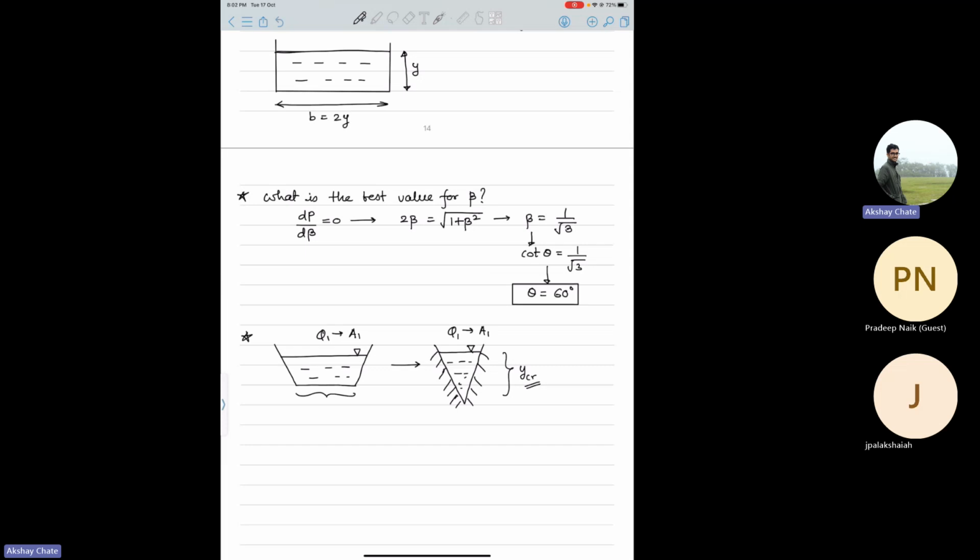But if we are talking about practical things like construction costs, there is also sedimentation, right? For a triangle, I think it will be more disadvantageous if there are sediments, because they can easily get caught in between the wedges, whereas for trapezoidal, they may flow along. So all other factors we have to consider, but assuming those are not important, I agree with what you are saying, but we have to do some calculations to get this y value, which will be the depth for that channel. Okay, sir. Thank you.